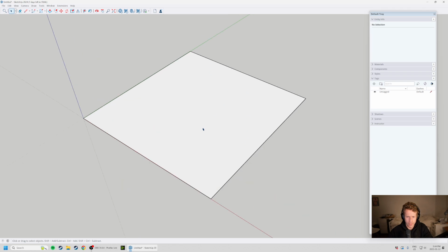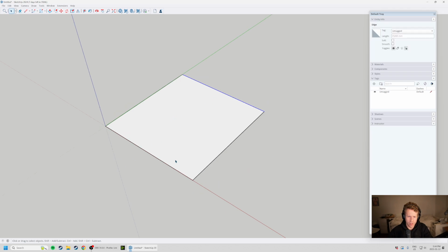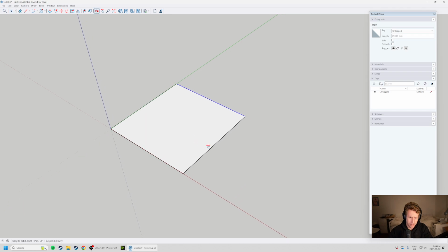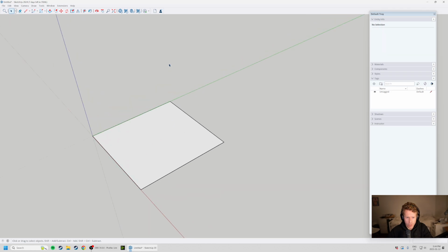So for instance, if I wanted to stretch this object, say instead of it being 25 meters, I want to make it 50 meters. You can do it two ways. You can either redraw it, or we can actually take this edge and move it. So if I click on this edge here and I come up to my move tool, move is M for those of us that like the shortcuts.